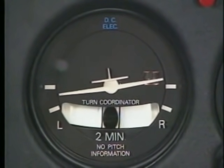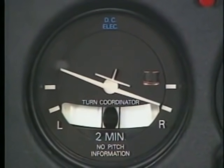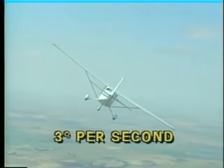One of the most important uses of the turn coordinator is that it enables you to establish and maintain a standard rate turn, which is the rate you should use for most instrument maneuvers. With the wings of the miniature airplane aligned with the reference mark, you'll turn at a rate of 3 degrees per second.